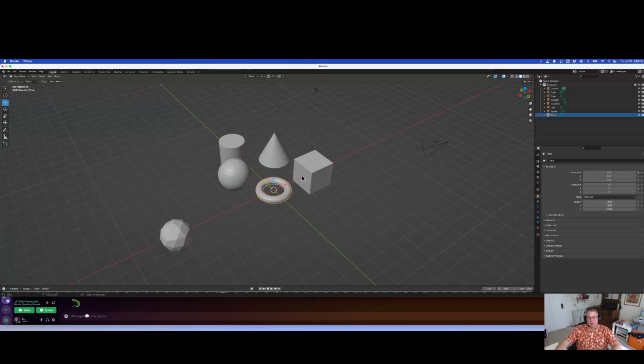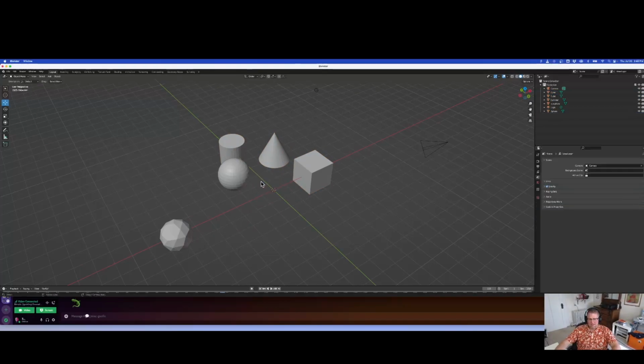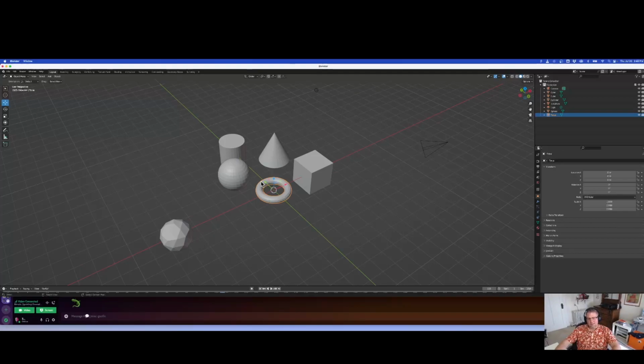Okay, cool. So I've got the ability to add something, Shift A. I've got the ability to select multiple things, press and hold Shift and click on multiple things. I also have the ability to delete something, X, and undo that, Command Z. The only other thing we haven't talked about so far is duplicating an object. So when I have an object here, I can duplicate it a couple different ways.